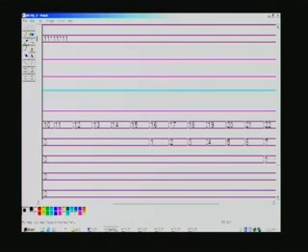Likewise counter 3 will stop only for 20 actually. Although it appears to be 21 here, it is actually 20 we have enabled the counter. The actual counting itself will take place only 1 clock later on, that is why it is deferred here. In fact, you can see right here the 0 must coincide with 20, that is the implication. So, we have precisely got the same thing earlier for 15, you can see 15 and 15 start here.